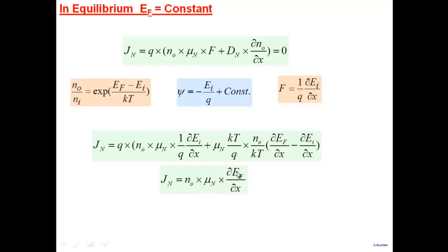Fermi energy, in fact, is related to, I'm sure all of you have done thermodynamics, right? Gibbs energy. Who remembers Gibbs free energy? Chemical potential. Anybody remembers chemical potential? So Fermi energy is nothing but the chemical potential. Chemical potential, if you remember, gives free energy per unit mole, and it tells us the direction of a reaction, or in which direction things will go. This is what Fermi energy tells us, in which direction my electrons will go. Wherever del EF by del x is high, it tells you the direction of electron flow. The gradient in Fermi energy is nothing but like the chemical potential.